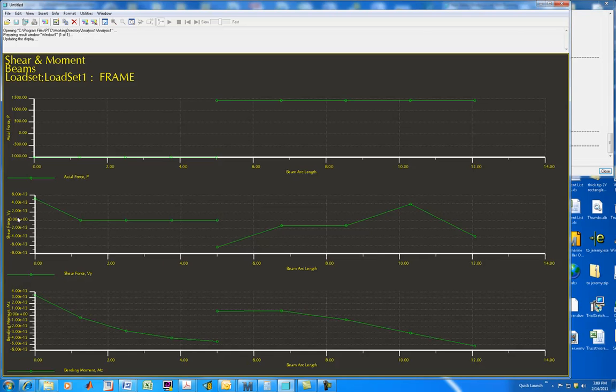Anything that's not 0 in all of these moments, that's just round off error. Same kind of thing is true for shear forces in the Y. Why is that? Because these are now both 2-force members. So there's not going to be any shear force in the Y. That's 10 to the minus 13th. That's round off error. All we have is axial tension and compression in the two force members. So that's probably enough for now playing with this beam.